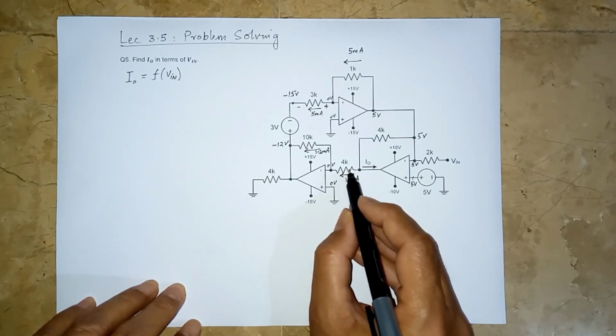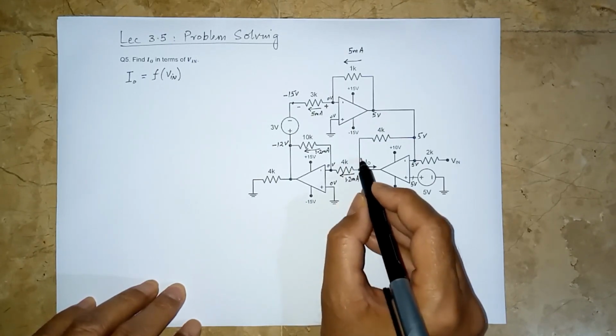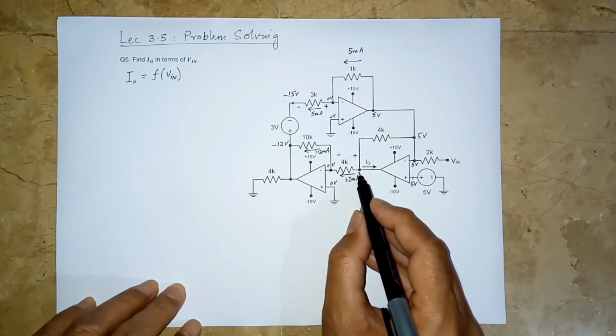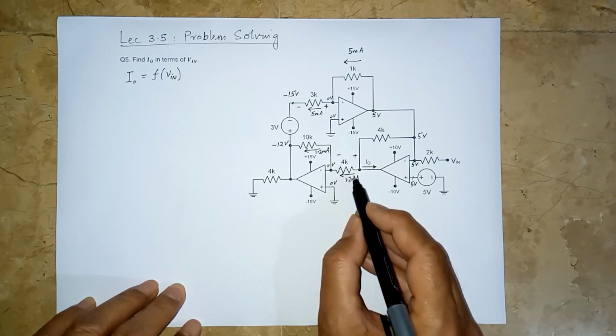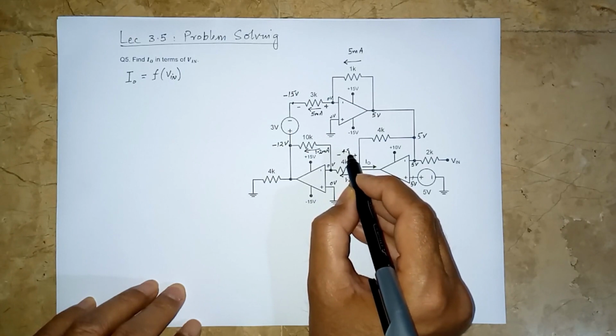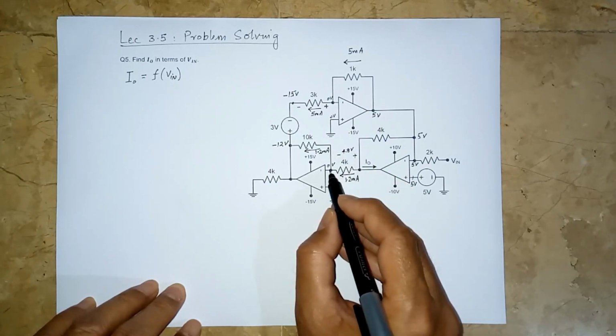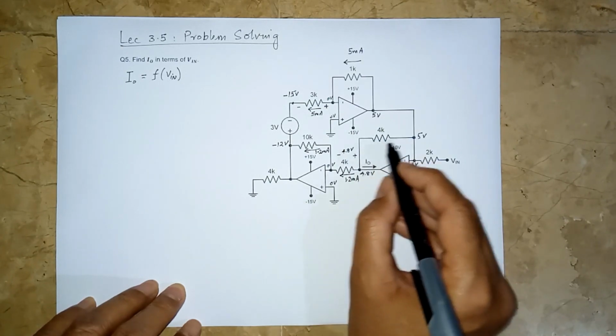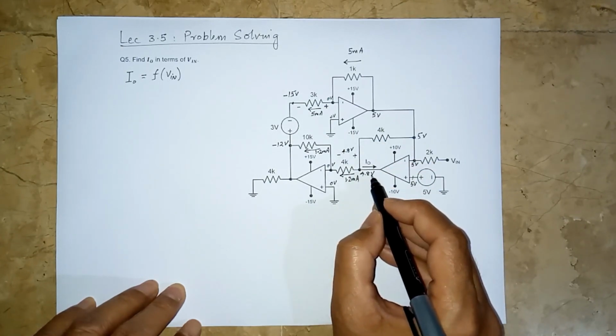and we can also find the voltage across this. This end will be positive, this negative, because this is a positive current entering in this direction. 4 into 1.2 is 4.8 volts. So 4.8 volt across this means this is 0. This must be 4.8 volts. So we know the voltage across this one. This is 4.8 volts.